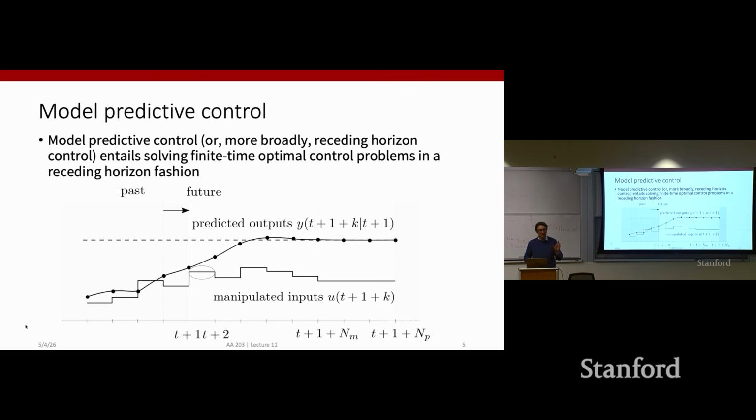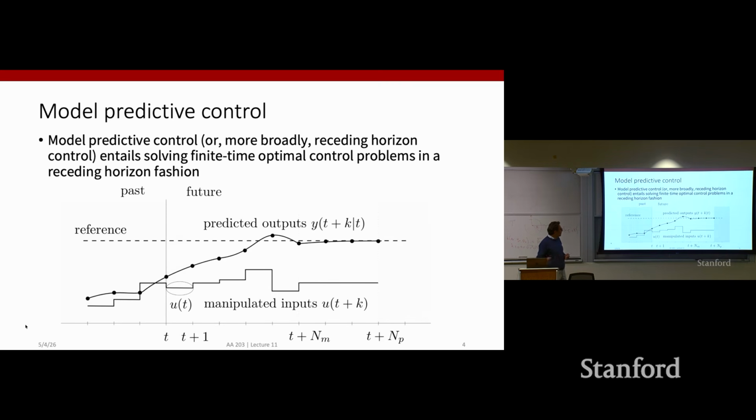Turns out that this is really a sweet spot between doing open loop optimal control and actually using closed loop information from the measurement of the state. It seems wasteful, right? Because you solve the problem over maybe a long horizon, and then everything that you have computed after the first time step goes into the trash.